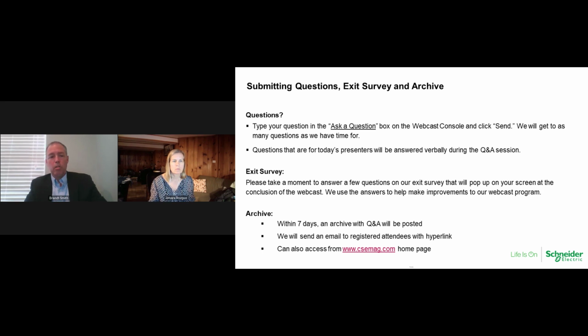There's a couple people that are using other gases, but those other gases honestly have as many problems, in some cases are worse than SF6. SF6, it may be a greenhouse gas, but it's the wimpiest greenhouse gas I've ever seen.